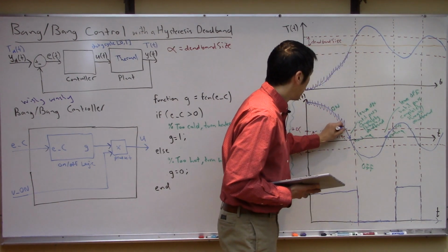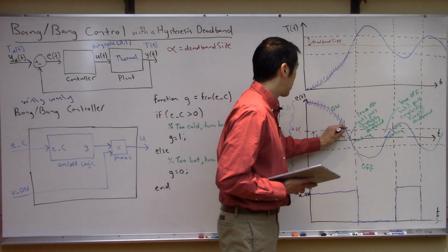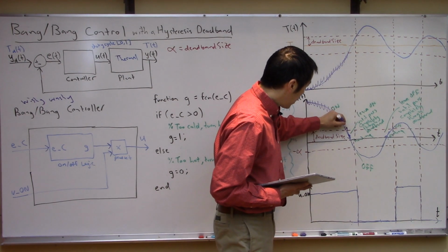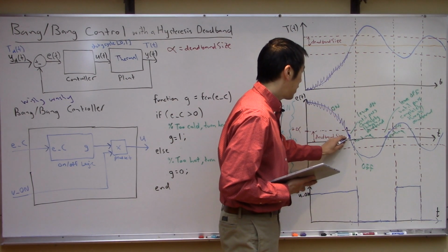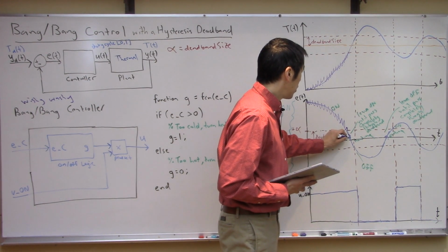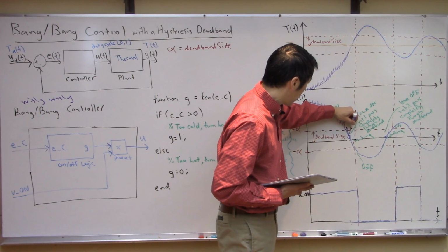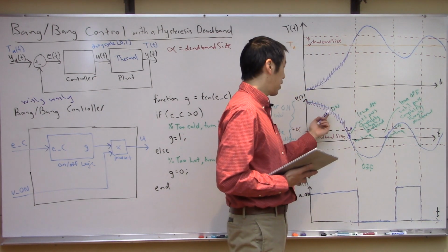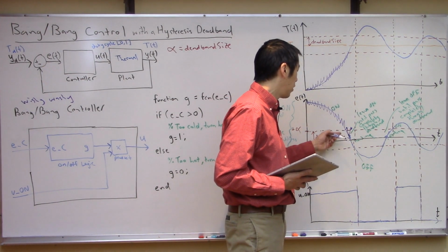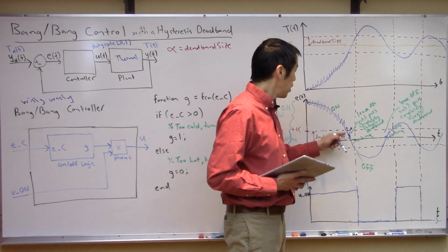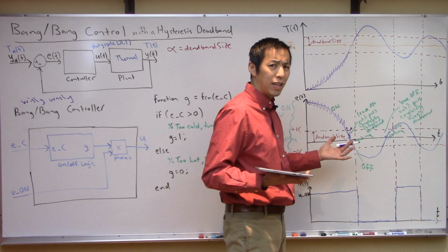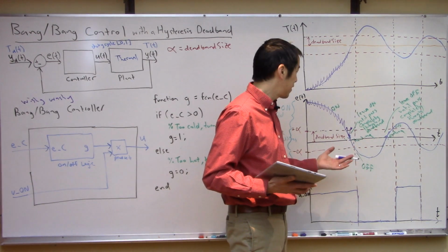Okay, so again, you are outside the deadband, you're on. But the noise bumps you back into this deadband, right? So you are on at this sample, and again, you stay on, even though you're out here. Now, say the noise bumps you out again, outside the deadband. Well, heck, you're still on. So even though you've bumped in and out, and maybe you are chattering in and out of the deadband, notice that it's on to on to on to on. So really, there's no chatter from the control signal, it stays on, right?